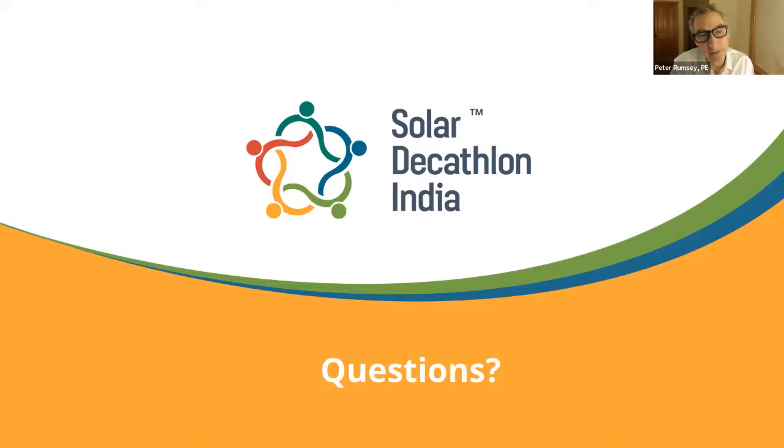The most important thing is that we have very good filtration. Our recommendation is that you use MERV 13 to MERV 15 filters. This is the rating of the cleanliness of the filter, and that will be able to filter out these small aerosolized particles, which can be the transmitters. So I think the best things you can do: social distance in an office building, wear a mask, and have very good filtration. Bringing in more air will help, but it's not going to fix the problem. Much more effective are filtration, masks, and distance.